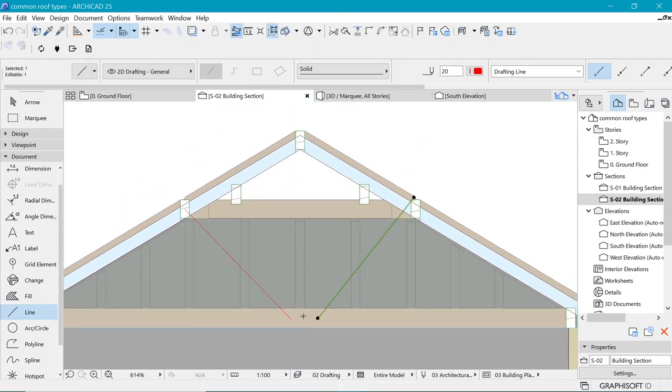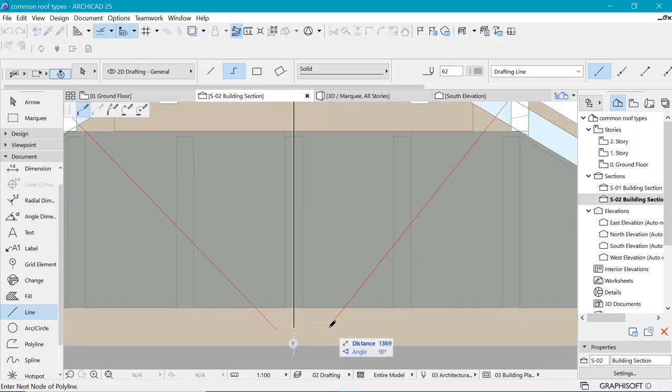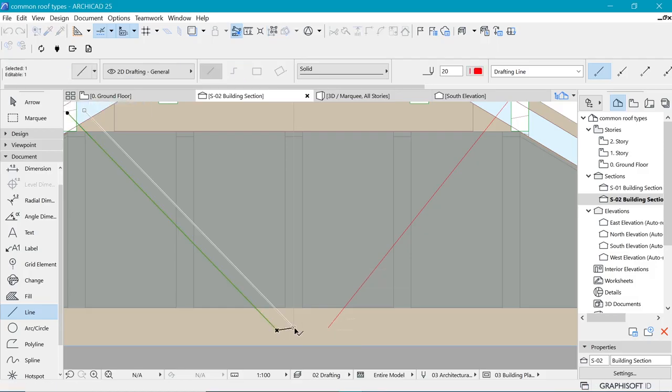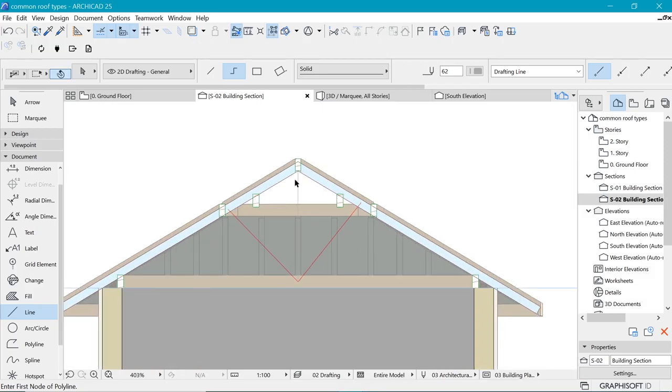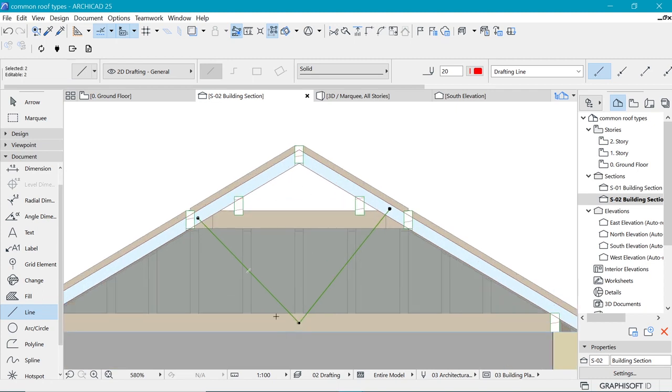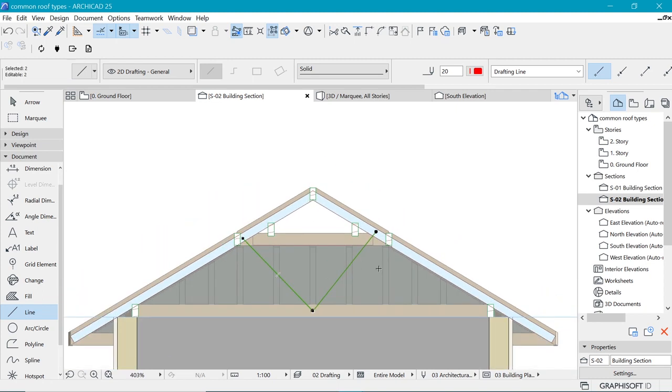And it is not looking quite good, so I'm going to pick the middle here, and I will make them come down here, and these ones as well. I think that will work. That does work. You can do whatever shape or webs you want in order to create this truss. Of course, if the span was a bit longer, we would need more webs for these kinds of truss.